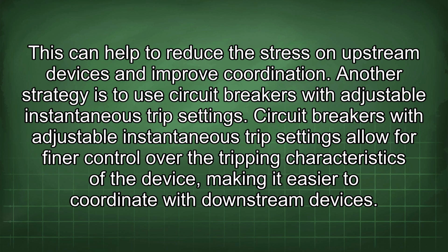Another strategy is to use circuit breakers with adjustable instantaneous trip settings. Circuit breakers with adjustable instantaneous trip settings allow for finer control over the tripping characteristics of the device, making it easier to coordinate with downstream devices.